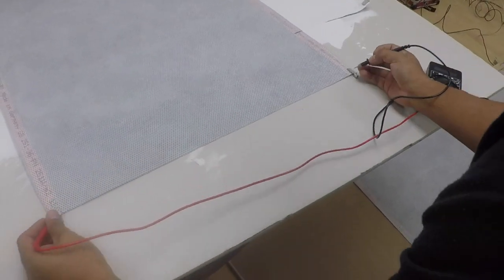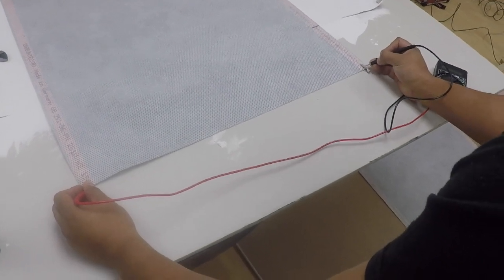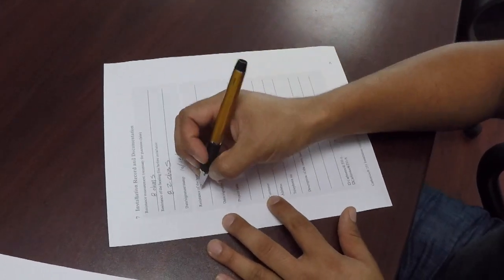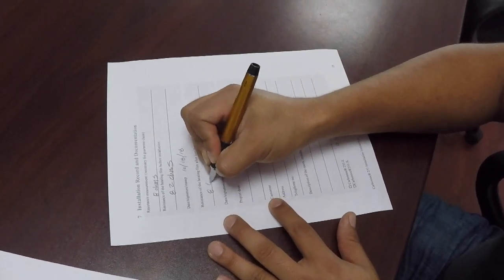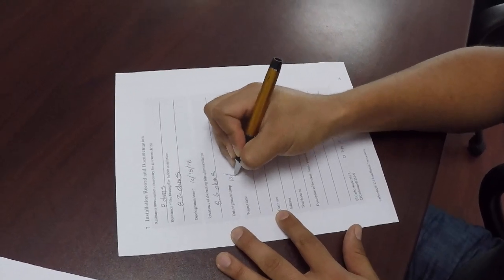Take an electrical resistance reading from the contact points. Electrical resistance level must be measured at the crimped contact points and must be documented for guarantee claim purposes before and after installation and plaster. Record resistance value in the last section of the installation manual.